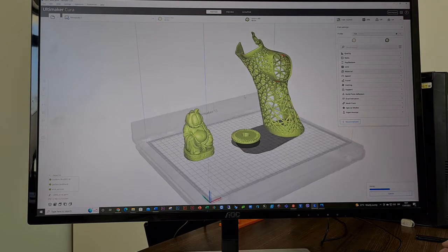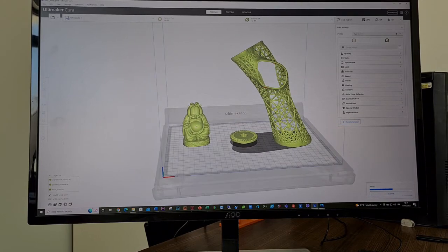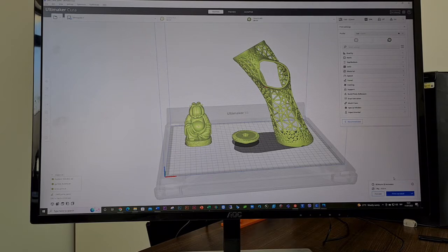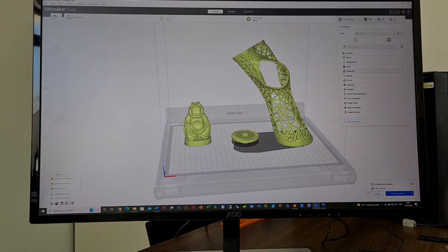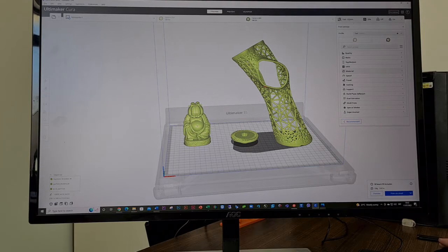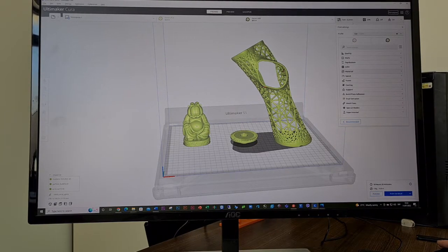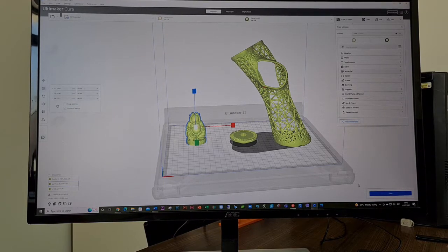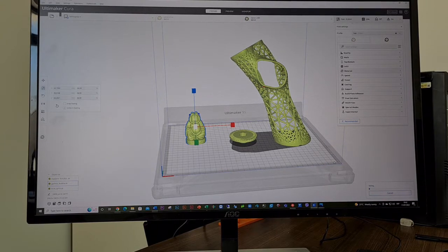But what is a very useful thing with 3D printing is, after the design and you set printing parameters, the software will prepare and you can see at the end the time which is necessary for these 3 objects to be printed, and you can see the amount of material which will be used, and you can easily calculate the cost, and you can determine whether you shall use this technology for production, or for example you can lower down some of those objects if necessary, and then after slicing again the amount of material will be less.